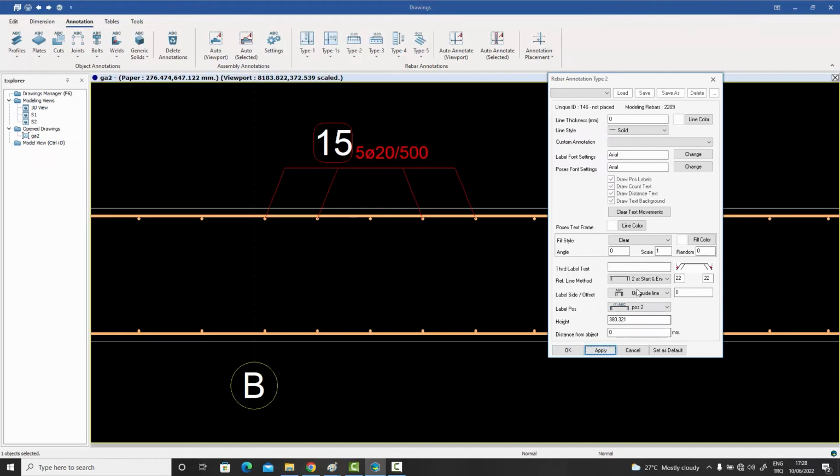You can reverse the sides. You can take it to the bottom or to the top, and this is very similar, so I don't need to repeat what I said. And once again you have this custom annotation over here where you can define your own type as you wish, and then that particular label will be displayed rather than these standard labels.